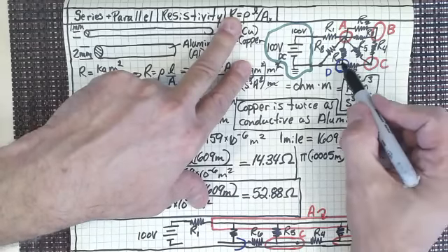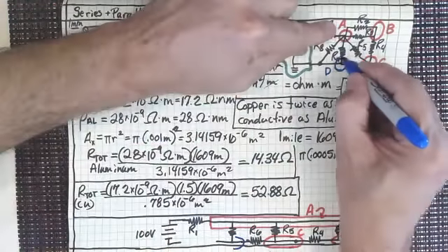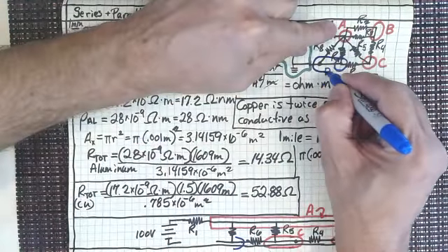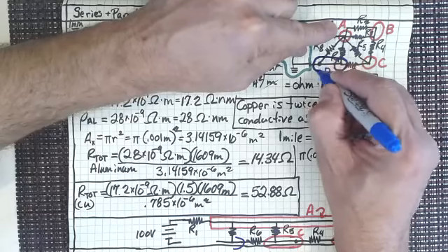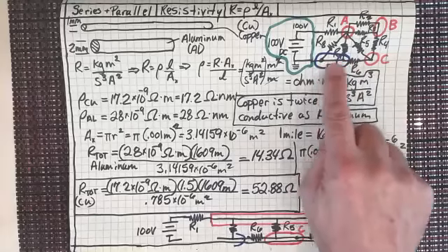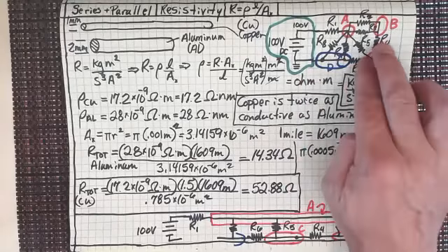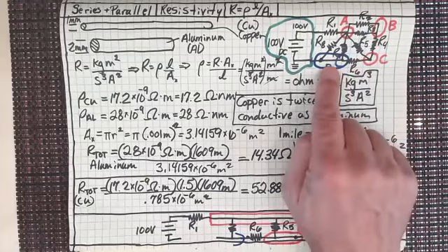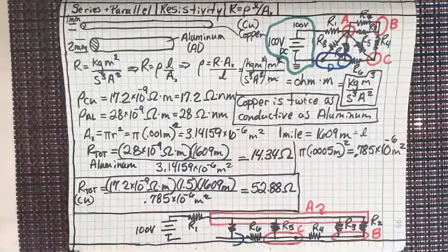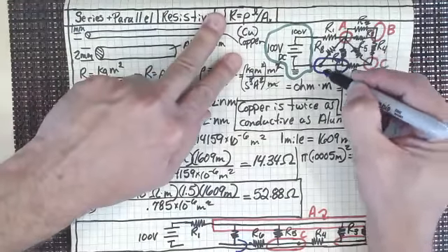And then, really, sorry that I just drew that there, because this node does extend over here. It's a short circuit, isn't it? So that whole thing is one node. It's all a short circuit there. There's no resistor there, unlike this resistor and this resistor, which separate those two nodes. So I'm just going to draw that. Those are all connected, A to D.